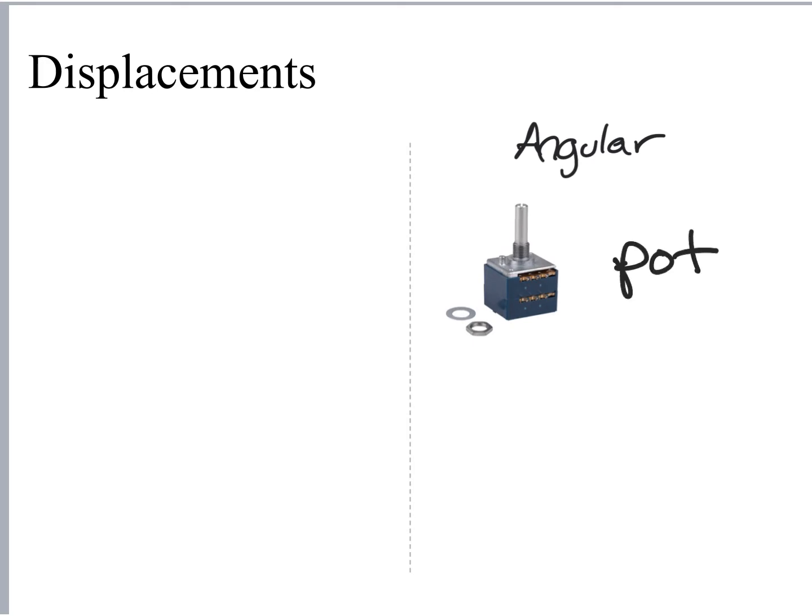And you'll notice that with this potentiometer, there are a couple of key features. Here we have what's referred to as a panel mount potentiometer. You see that there's a set of threads here that go with the nut and the washer that are seen on this. Those threads allow you to mount this thing to a stationary panel.